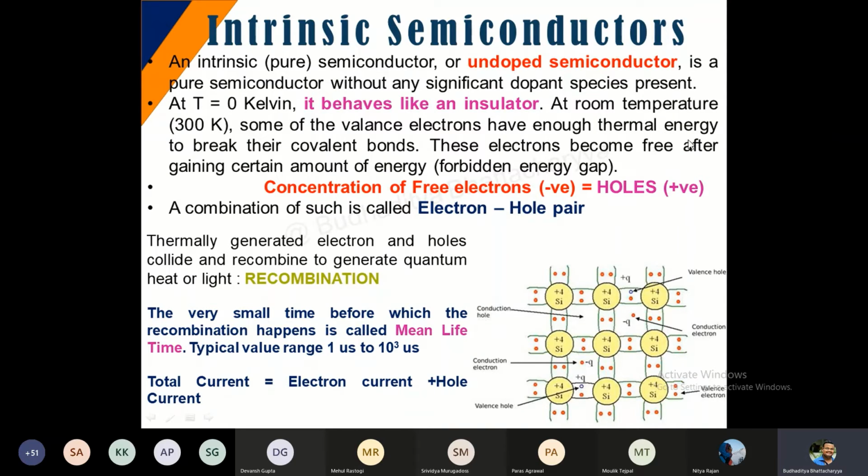That thermal energy will make sure that the covalent bonds are breaking inside the molecular state, and the free electrons will gain a certain amount of energy. So that Eg, the small value of the forbidden gap that we were discussing with respect to semiconductors, the free electrons will be energetic enough to go on top of that forbidden gap and reach the conduction band.